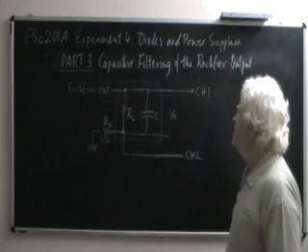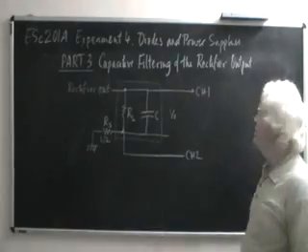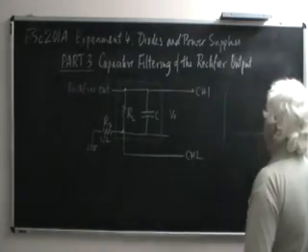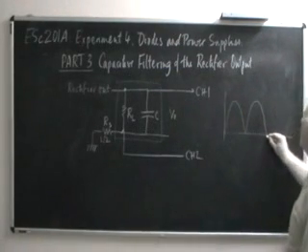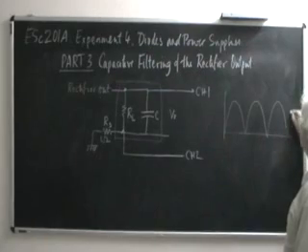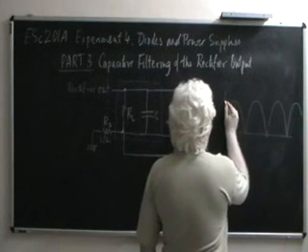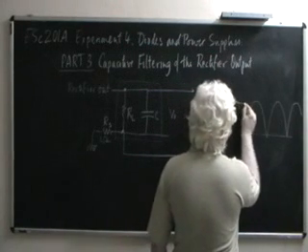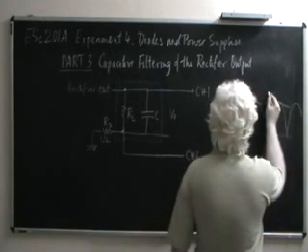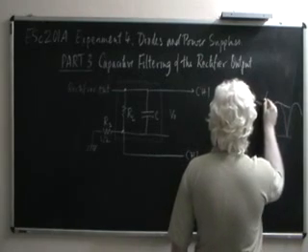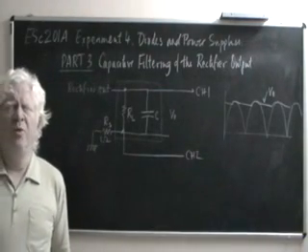So now you see what happens. This channel 1 voltage will essentially tell us how constant the voltage is. This we already plotted for a sinusoid, for a full wave rectifier, for example. We would get an output voltage that goes something like this. This would be VO, the output voltage. This is what it would look like.